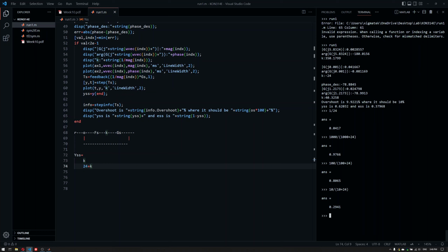When you are trying to design a p-type controller, you're trying to increase the magnitude of your controller, using a higher gain value. At the end, you can check if your design is correct or not. Because for this error value to drop down tenfold, we need a much higher value than 40. If the DC gain of the whole controller, Fs times K, is larger than 40, you're probably on the right track.